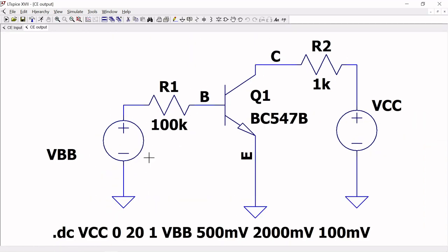In the output characteristics, the only thing you want to understand is that I want to find different values of IC for different values of VCE. So I will change the VCE value. For the changes of VCE, you will be finding what the current is. During that condition your IB will be constant. Here I am keeping the input voltage constant for the different set of values. Theoretically we say the changes of current will be observed when you change your VCE for different values of input current.